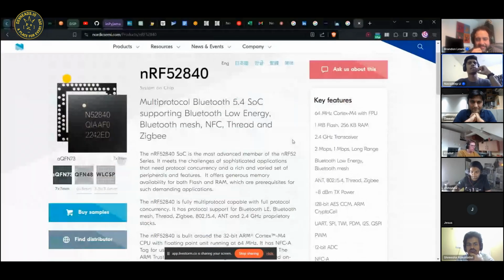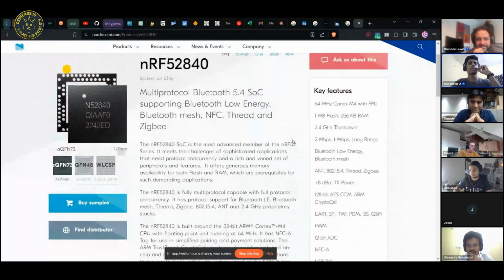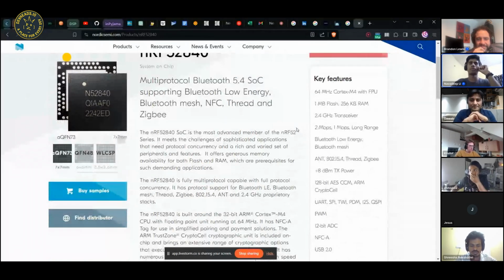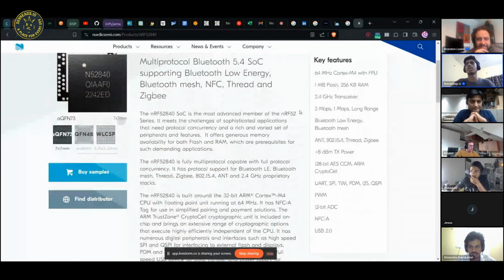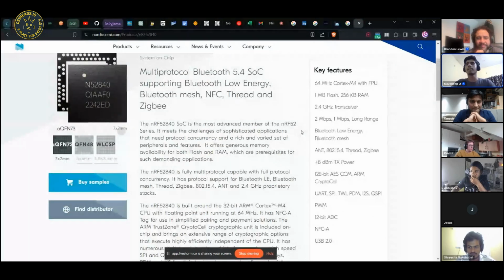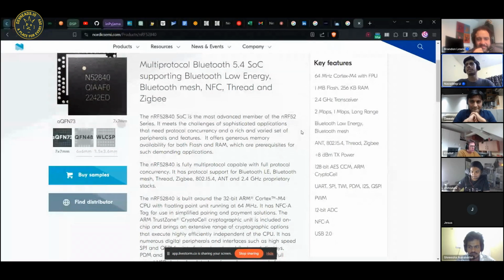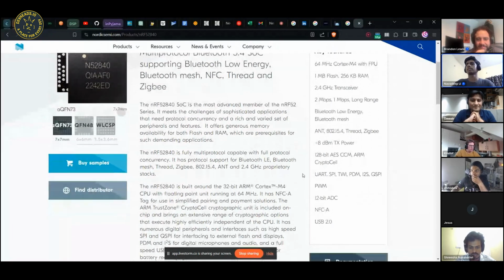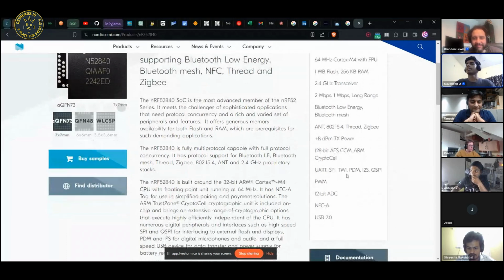Then once I'm here, this looks like a good point for me to dig deeper and look at what features it has. The frequency band: does it support 5 gigahertz or just 2.4, and do I want 5 gigahertz? Then look at what peripherals are there. Say for a Wi-Fi clock, I might want a display, or a pixelated NeoPixel sort of thing, where I will display the numbers.